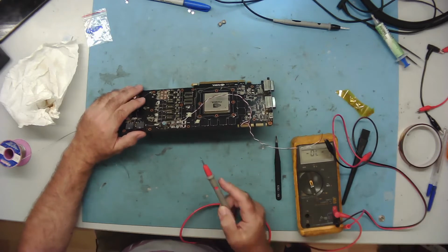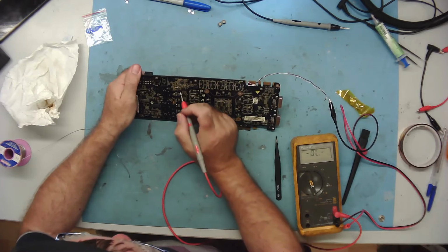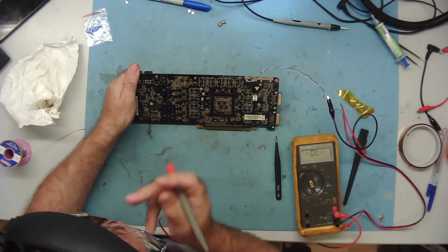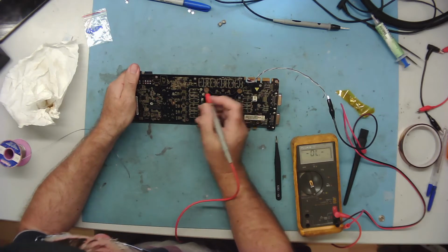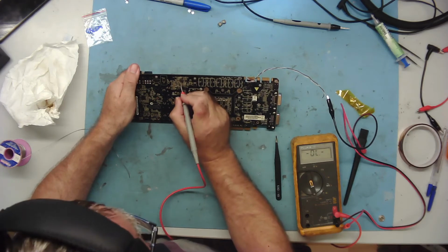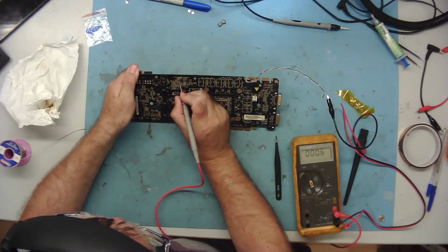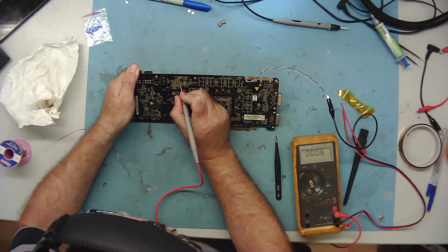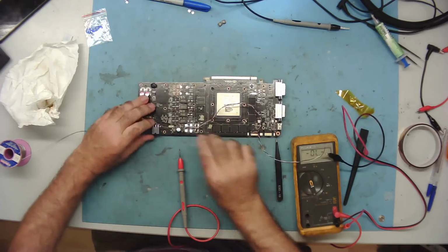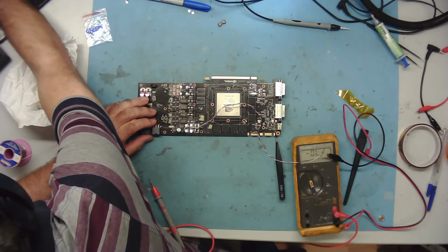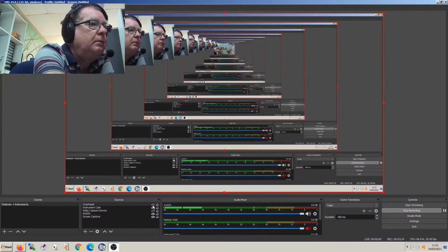And then I've got the other lead. What I can do now, I had a look on the data sheet, and this chip, it's pin 1 and pin 18 that go to the gates. So I know this end of this resistor goes to the gate, the other end must go to the upper gate and lower gate pin on here. I'll show you on the data sheet in a minute. So, yeah, there it is. That's pin 18, so pin 1 will go to the other one. Let me show you on the data sheet what I'm actually doing. Let's see. Data sheet. Okay.